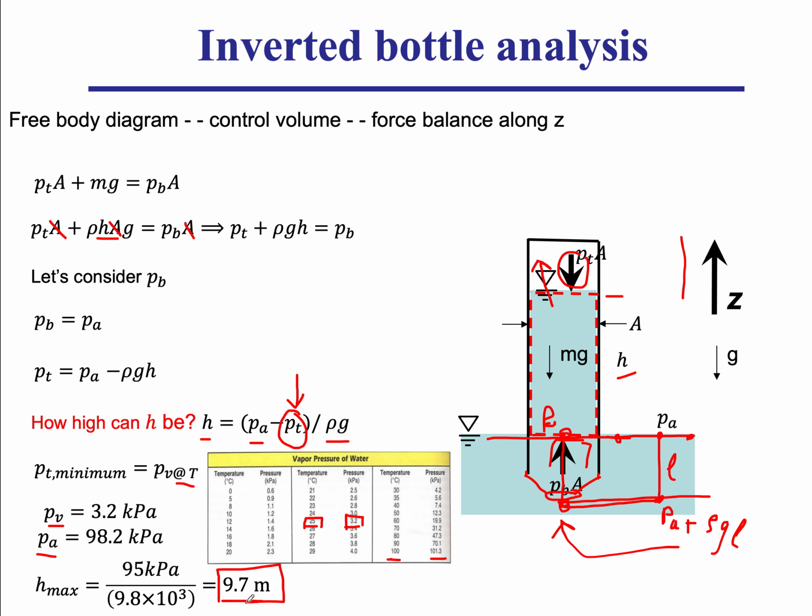So if you draw a well that is 50 meters deep into the earth, and you place your pump at the surface outside the well on the ground, and you take a pipe, the suction side of the pump, you stick it down 50 meters into the well, you turn the pump on, you're not going to get anything. Even if you prime it, whatever you do, that's not going to happen.